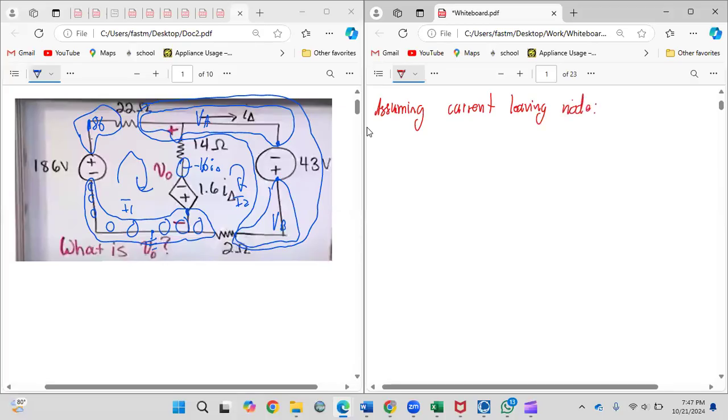So we start. We only have one node that we need to do the equation for, which is this one here. I like to draw dots at the endpoints. So I have 1, 2, 3 endpoints. So I know I have three little things. So remember the little thing I showed you. If the current is going out, the same equation, where you're coming from, so the node you're coming from minus the node you're going to, divided by the resistor in between them.